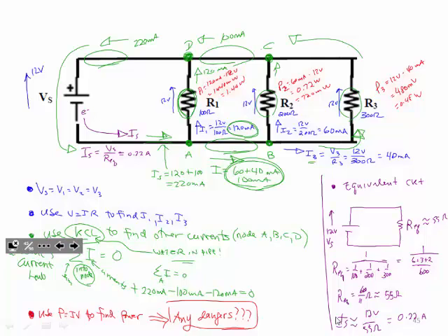I mean, this is 12 volts. 12 volts here, so we have 12 volts the whole way. Why is that number a little bit high? It's almost as if I have additional voltage there. Or that's showing the resistance. This is voltage, and that's current. So why is that showing a little bit more current than I should have? 5 milliamps extra. On our resistors, that means our resistor is probably a bit low. We'll check it and we'll see.